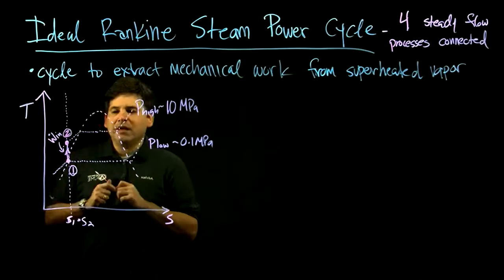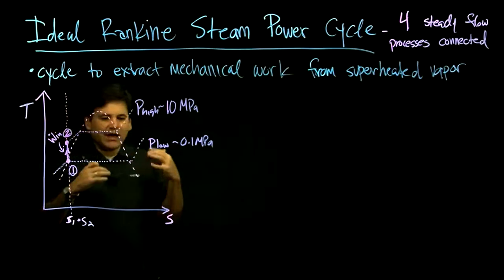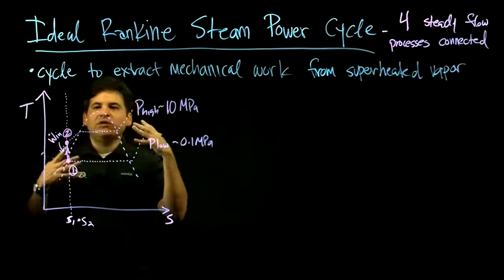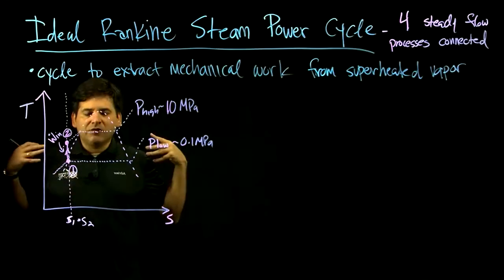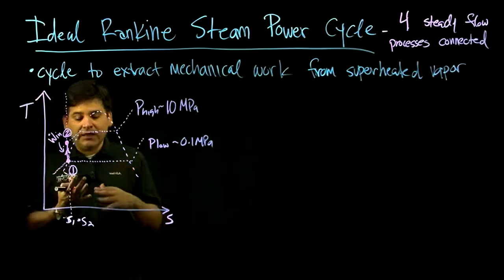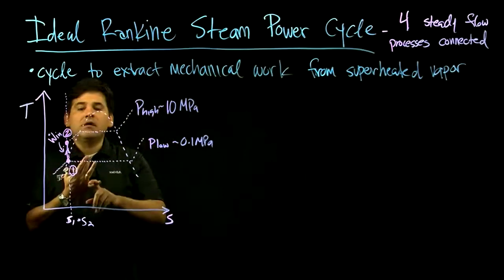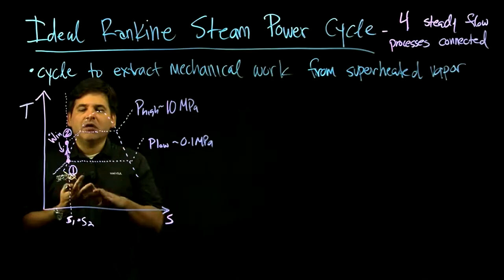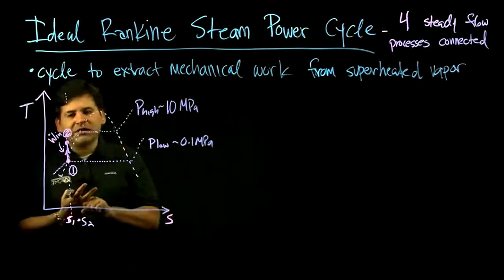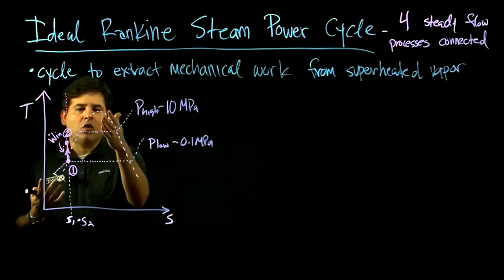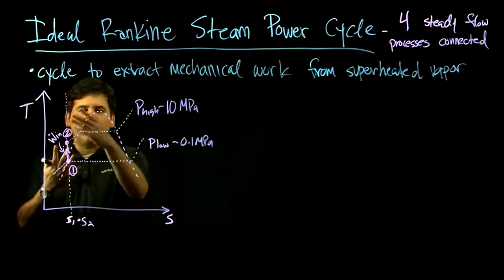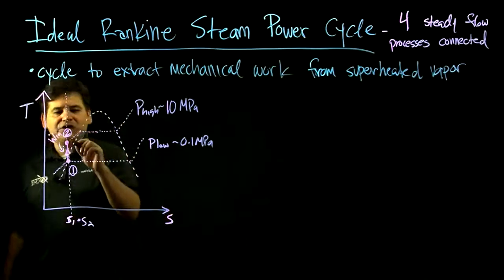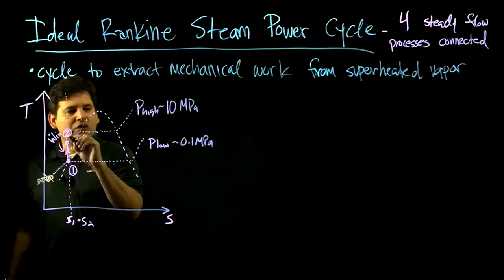From the outside, you have this water in compressed liquid state, and you expose it to a heat exchanger where energy comes in from the surroundings at high temperature frequently. This is applied to coal power plants, nuclear power plants, and others where this liquid water gets boiled by the coal fire or boiled by a nuclear reaction from the outside. When you add that energy in from the outside, you keep the pressure the same.